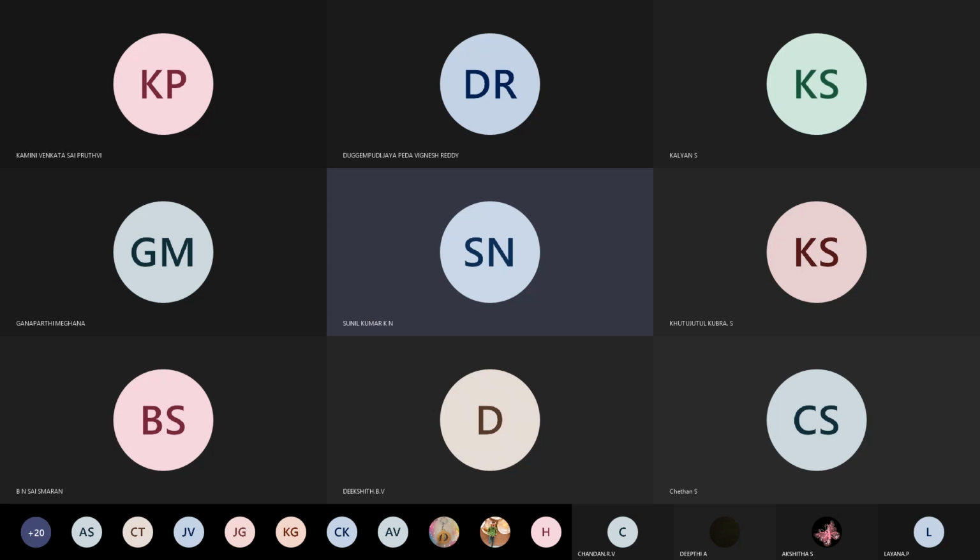One is directly proportional to vgs, and the other is proportional to the square of the gate to source voltage. So we have two terms: Kn into VGS minus VT into vgs, plus half into Kn into vgs square. Which of these contributes is what we are going to see right now.